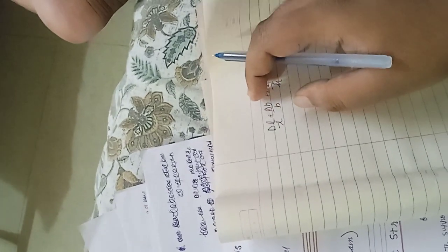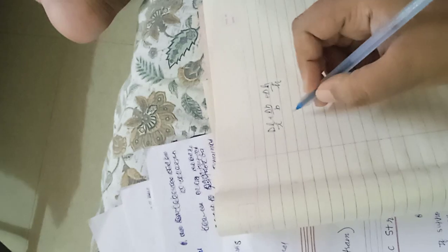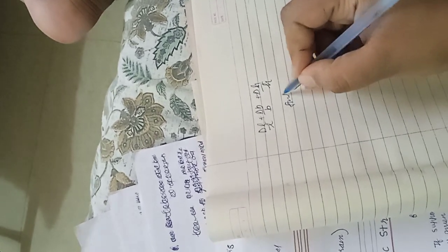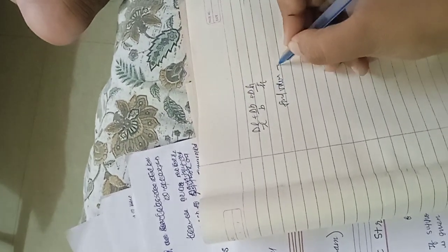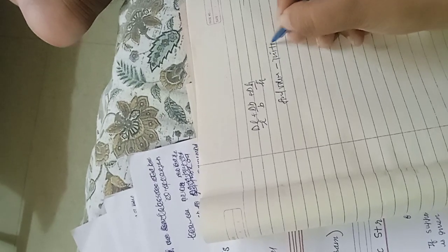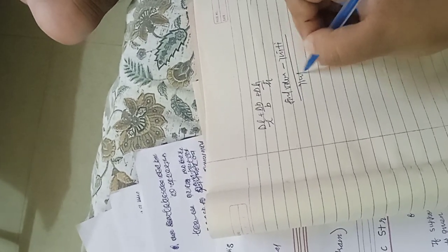And if it is not symmetric, then the volumetric strain is just the final volume of the body minus the initial volume of the body, divided by the initial volume of the body. So if any random shape is given, this is the formula. And as there is a volumetric strain, it can only be caused by normal stresses. Shear stresses have no effect on volumetric strains.